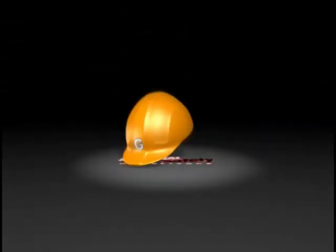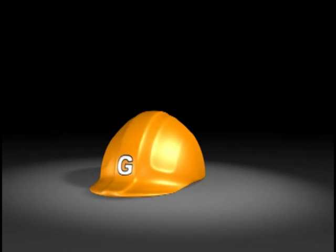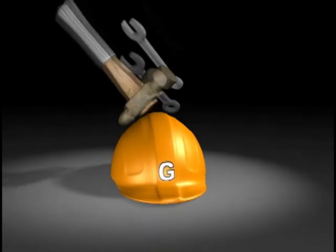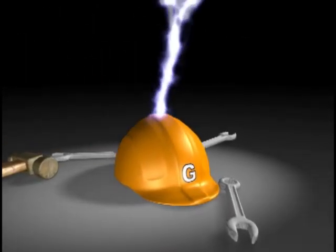Class G hard hats, which were formerly Class A, are for general service such as mining, building construction, lumbering, and manufacturing. This class provides good impact protection, but limited voltage protection only up to 2200 volts.